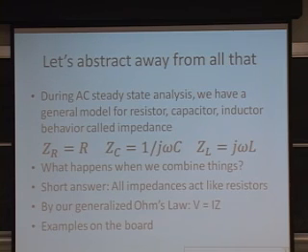So at resonance, what happens? Yes, there is a voltage difference. What happens at resonance is that you have some voltage difference across this capacitor, and you get the exact opposite voltage difference across the inductor. So that is how they end up canceling each other out.